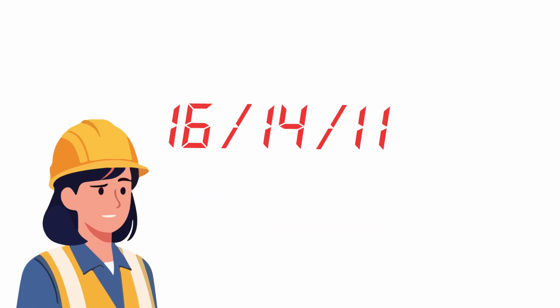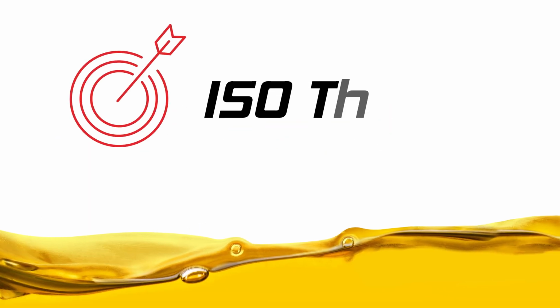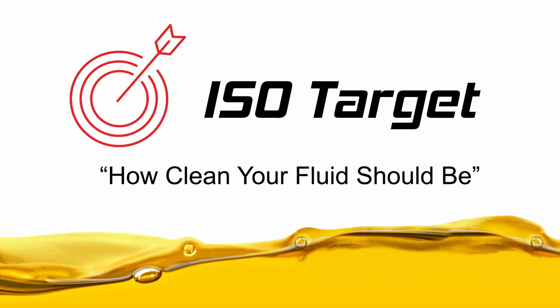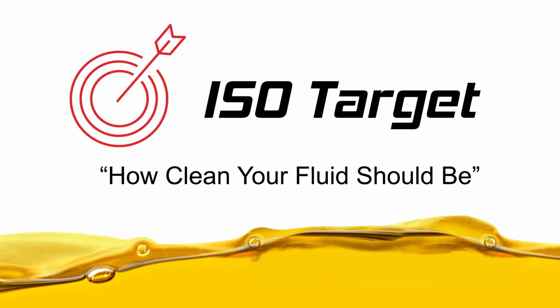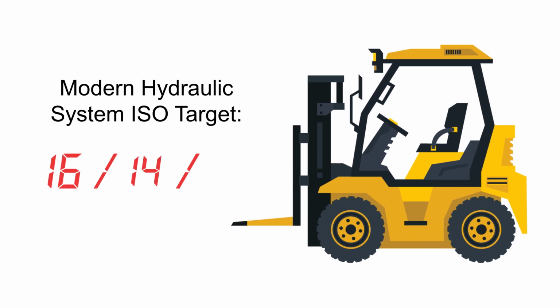But without a benchmark to compare to, ISO codes are really just numbers. That's where ISO targets come in. An ISO target is an ISO code that represents how clean your fluid should be to allow your machine and its components to have a normal operating lifespan. ISO targets are usually manufacturer recommended. A common ISO target used for a modern hydraulic system is 16/14/11.